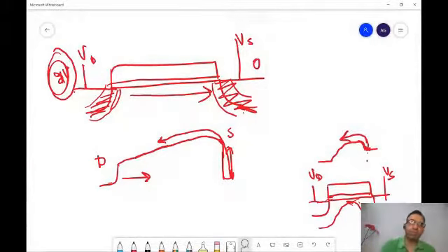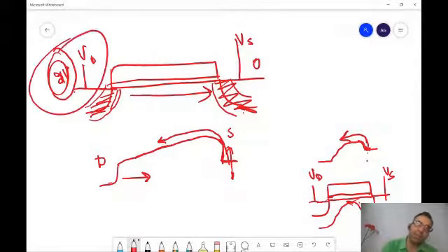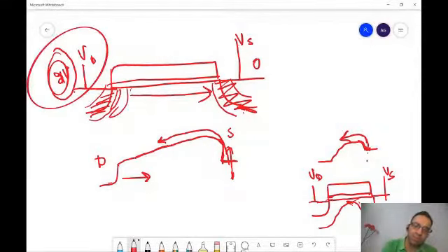That is what I'm saying. Because it's 2 volts over here, the overall energy is lower over here, and because it's high over there, the source is 0, so this energy would appear higher, but there is this barrier, and this VD over here, the change in depletion width that it causes does not impact anything on the barrier on the source side. Whereas when you apply a high VD over here, it causes a change in depletion width in such a manner that the source also starts to get impacted. And therefore the barrier reduces.